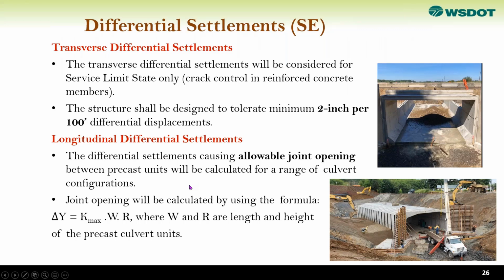One thing important in buried structure is differential settlement. Once we put these segments together, as you can see, they become one big unit. And when they become one big unit, we may have a transverse differential settlement or longitudinal settlement that could be creating some stresses in this overall structure.